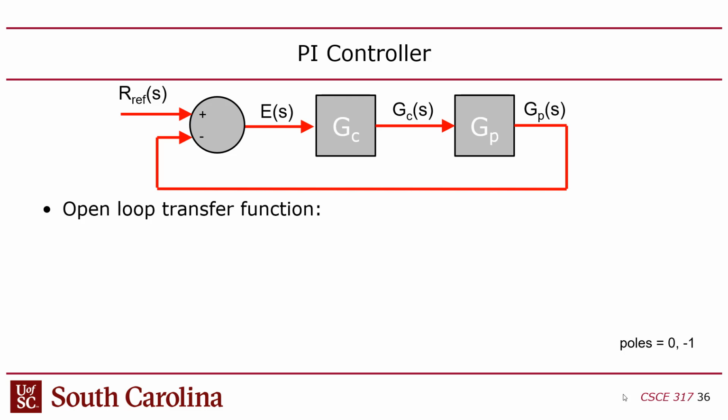derivative term. And the integral term is about if you start spending a lot of time away from the set point, the more time you spend away from the set point, again, you want to give it extra kick to get it there, right? So that's the idea of those two terms. And then of course the proportional is just saying, if you've got error, you got to kick it into whatever, plus or minus to get to your set point.